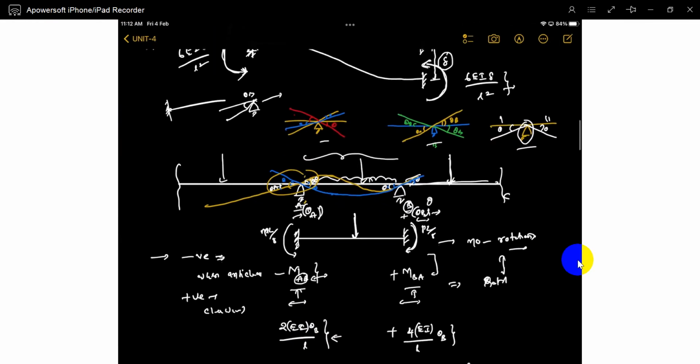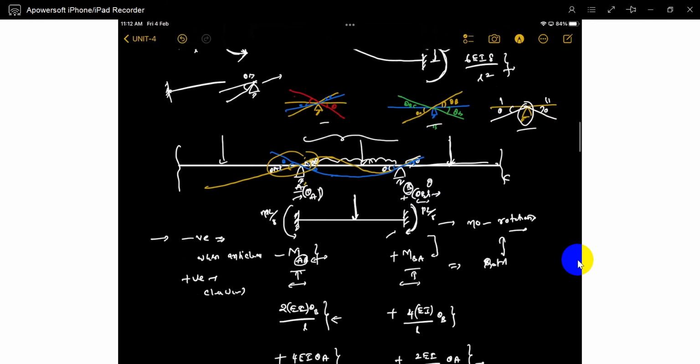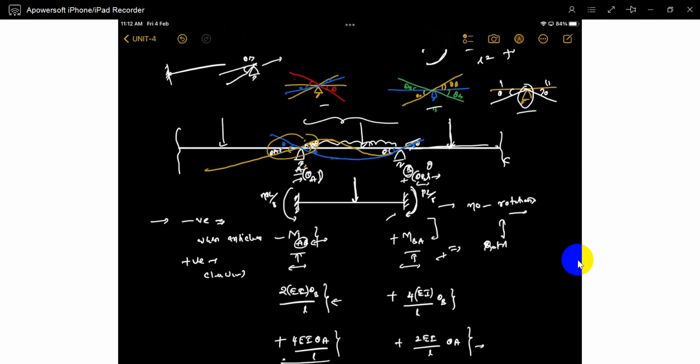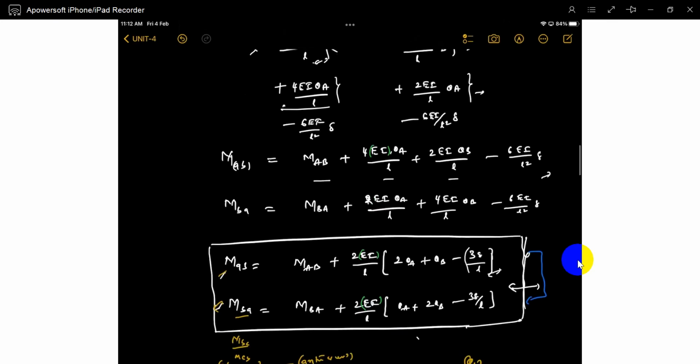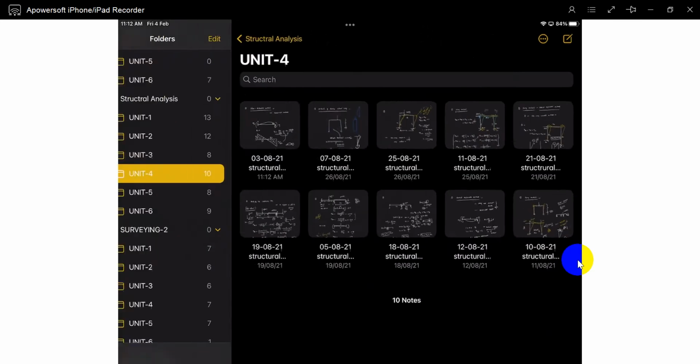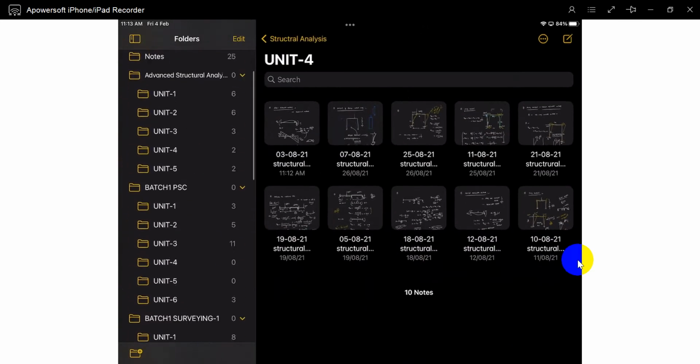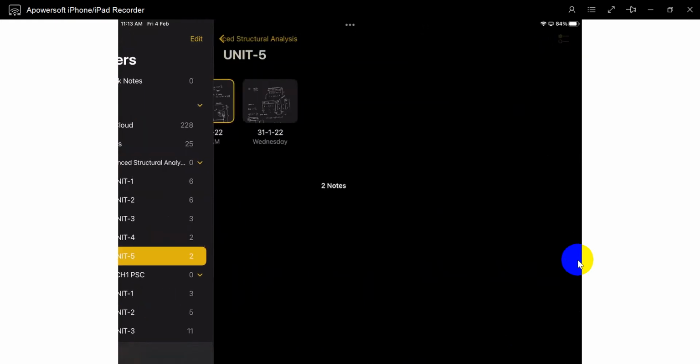First we restricted everything. We developed those movements. Later, finally, the release of those due to application of the forces. And finally, the deformations are released. Due to release, how much force is generated, the resultant only we write. Okay, that's it now. That's the whole slope deflection method. So if you include this also, support settlements. I explained previously. If you want, go check it.